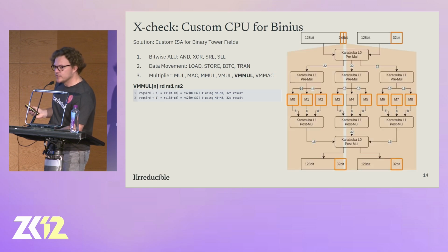But now this is very interesting. You have the same hardware, the same silicon, quote-unquote, all the logic gates, but this time you are doing 8 bits times 32 bits. In software, if you are doing this on a GPU or whatever, you probably need to go through different pipelines and registers, but here we try to recycle and reuse the same hardware.